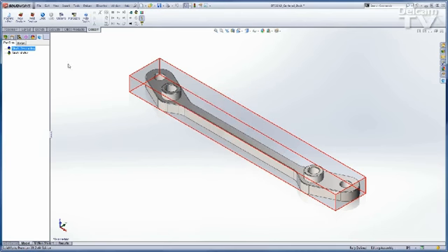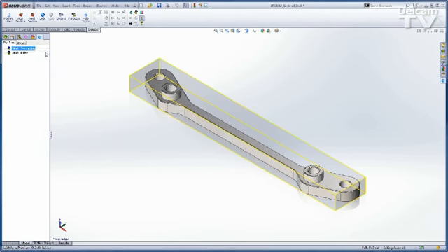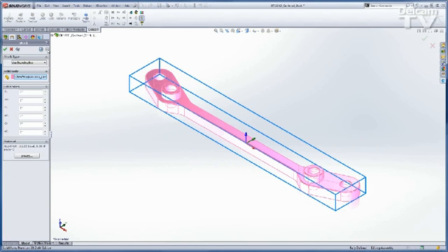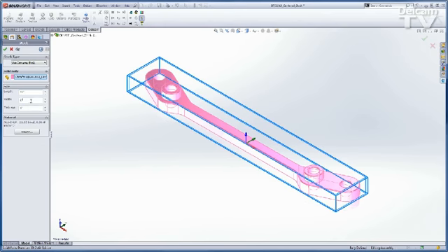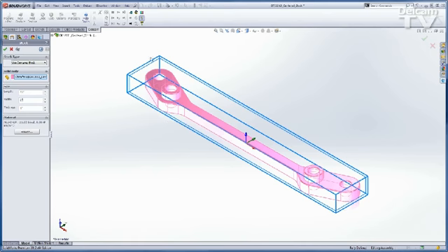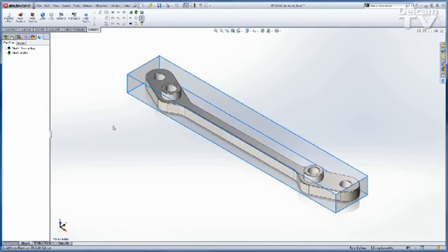I'll cancel that and we'll go back and edit this stock. Skip over the stock axis back to the stock definition, and here you see the new type, use centered block. And I can come in here and put in whatever numbers I want now. I can see my current stock block dimensions. I put in something like 13 by 2 by 1, something a little more standard, and you can see the block update. I'll click OK.